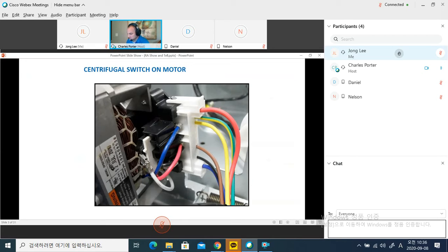So you've replaced whatever you've replaced. Let's say the heater coils are broken, so you replace that heater box assembly with the coils. You'll put her back together. Obviously, when you're inside a dryer, it's always a good idea to check the rollers and make sure they're rolling smooth, and all that normal maintenance stuff, vacuum it out for them. You put it back together, test the unit, and make sure it's heating. You'll explain the repair to the customer and thank them. And that'll be your last thing.